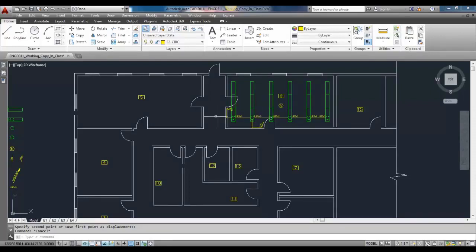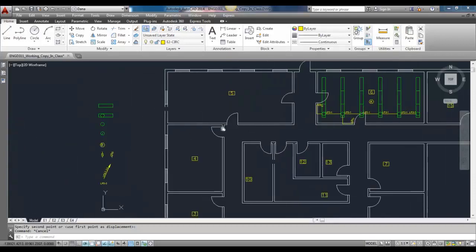So we're going to have LP3-1, LP3-3, and LP3-5, and they're all going to be connected through the same conduit because they're going to share a common neutral. So I'm going to speed up the camera here a little bit. I'm not going to be doing any talking, but you can actually see now how I lay out the rest of the rooms.